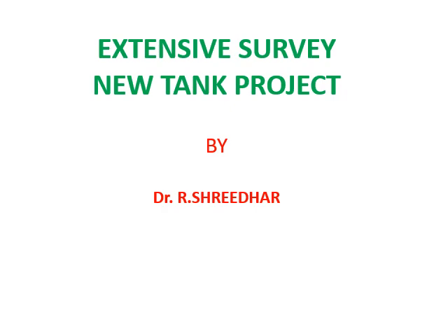There is a wrong feeling that when we do capacity contours, from the capacity contours that are generated, we can calculate the catchment area. Actually, it is not so. Many of the students do use the same capacity contours for the catchment area. So you should know that the catchment area and the reservoir area are totally two different quantities. The catchment area should be got from the topo sheet, and the reservoir area can always be calculated from the capacity contours that you have generated after doing a total station survey for the reservoir area.